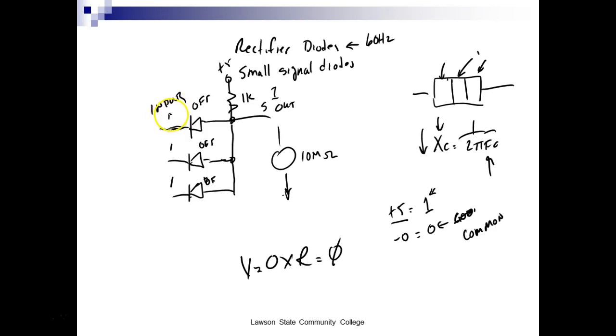So let's say I come over here and connect this to 0 volts, which is a common. So now this cathode is pointing toward negative. This is pointing toward positive. The diode turns on. How much voltage is the diode going to drop? So what would my output go to now? We're not even concerned with the rest of them.